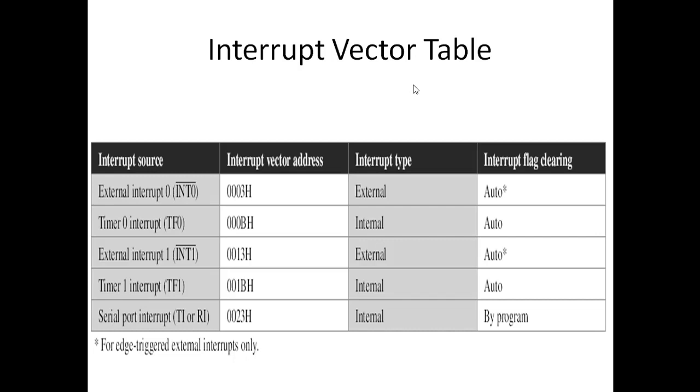Now keep that in mind. Whenever a microcontroller is providing service to an interrupt, it needs to perform certain tasks which a peripheral is demanding or anything else that is generating the interrupt. For example, the interrupt is being generated at INT0. As soon as the interrupt occurs, the microcontroller will suspend the execution of the current program and go to the vector address of the corresponding interrupt.